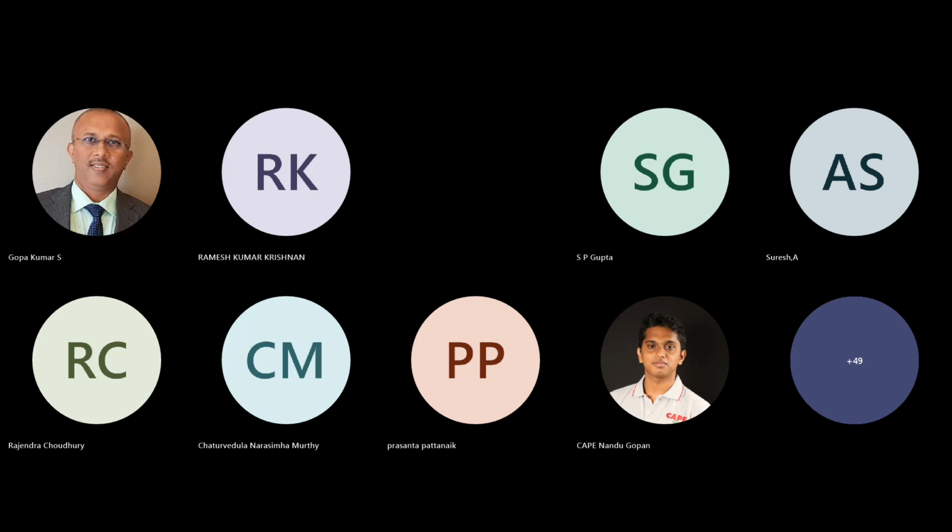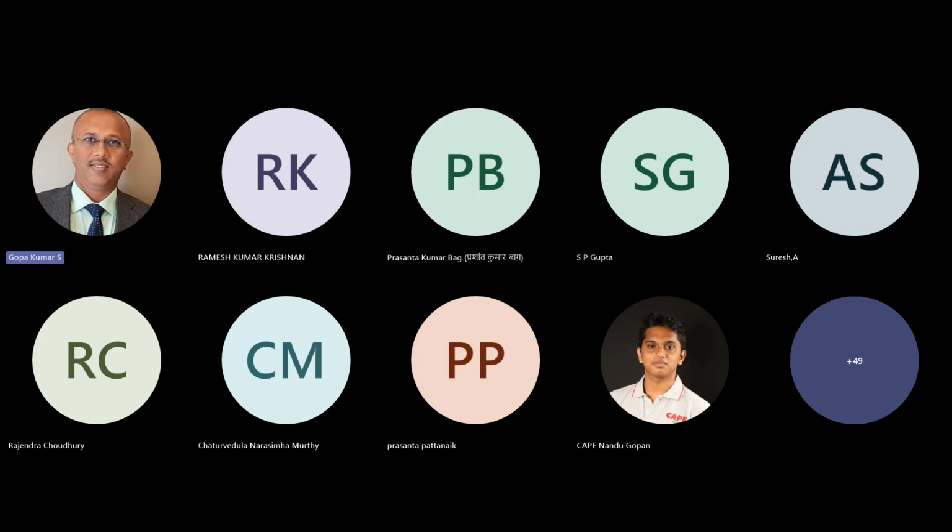Actually, what system earthing he is getting from the distribution company is the first question. Is it a TN system or a TT system? This is the first question the prosumer is going to ask. Then, there are different types of prosumer installation: individual, collective, or shared. Three types are there. If he is an individual customer and knows that the incoming system is a TT system, then he can decide the kind of topology he has to follow to achieve safety.